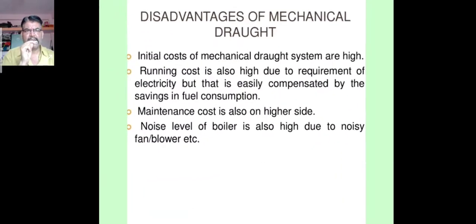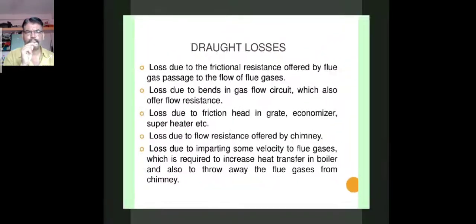So again there are some disadvantages. Maintenance cost is also higher. The initial cost of the mechanical draught system is high. The noise level of the boiler is also high due to the noisy fan or blower, etc.